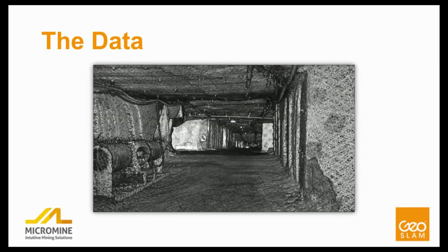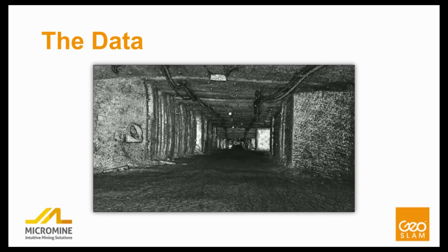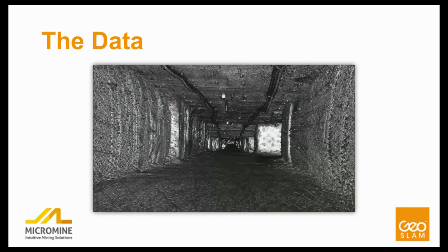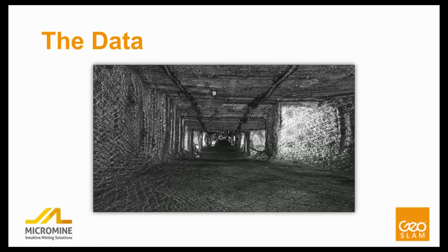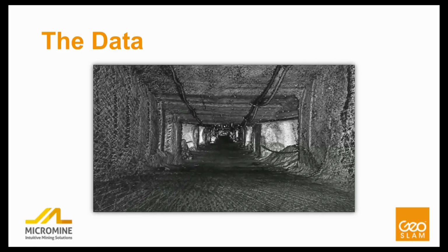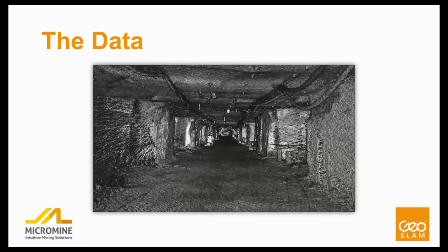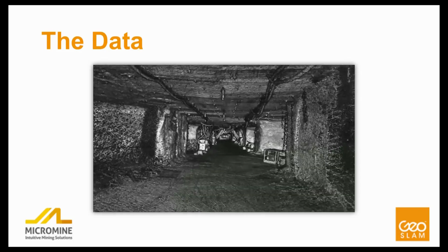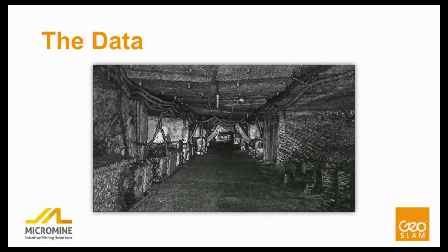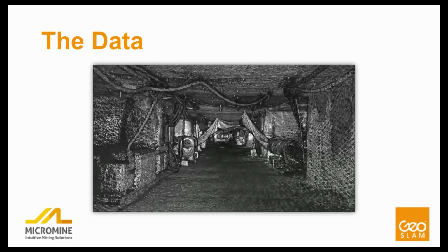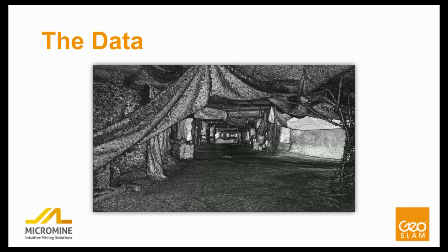And then this is what the data looks like. It's very, very powerful data, very clean, and this is deliverable then near enough straight away. There is a process when you capture the data. You do have to post-process it. You actually run the SLAM on your computer, and it normally takes about half hour to process to create this very dense, highly accurate point cloud.